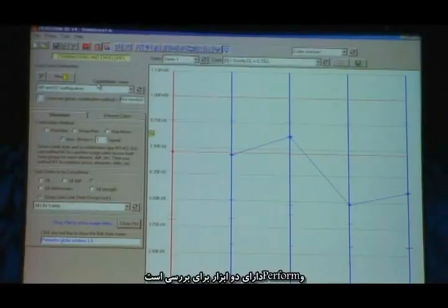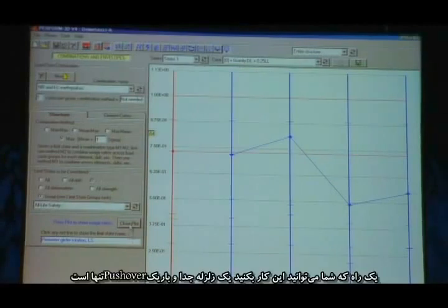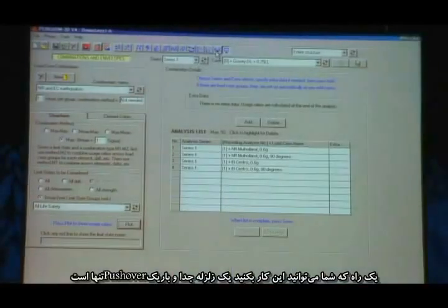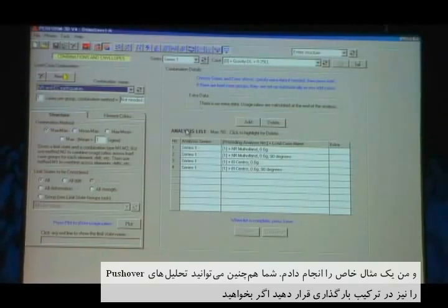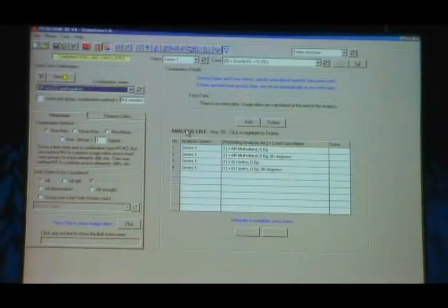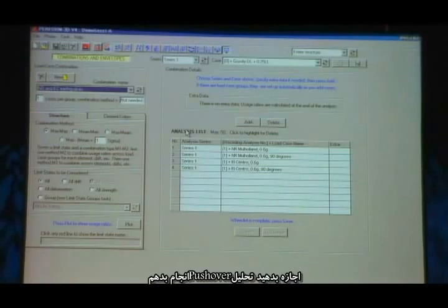And Perform has got these two tools here. The one we looked at where you can do a single earthquake or a single pushover, actually, if you wish, and the one where you can do a combination, and I did one particular example. You can also combine pushover analyses if you wish. Now let me do also a pushover analysis.